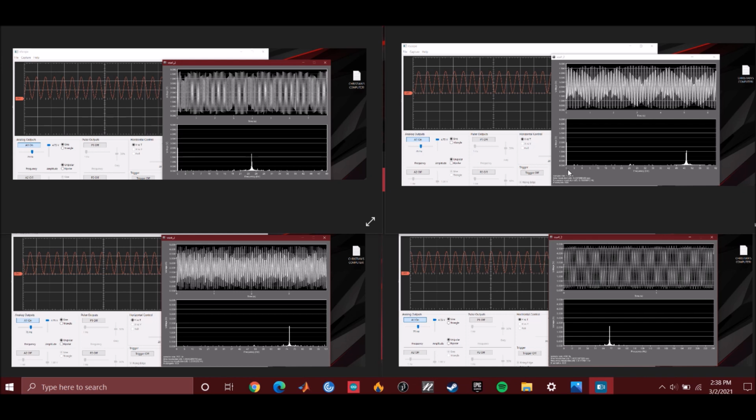So on top right, you'll see we have a frequency of about 126 Hz. Yesterday, I was able to get that frequency to 142. However, today I cannot, but I did perform all my calculations with 142 as desired and actual, and that programming can be seen in my code to make it 142. Nevertheless, for 75 Hz, we have aliasing at 100 and 142 Hz, as well as 200 Hz, but we get a cleaner square wave at around 500 Hz.